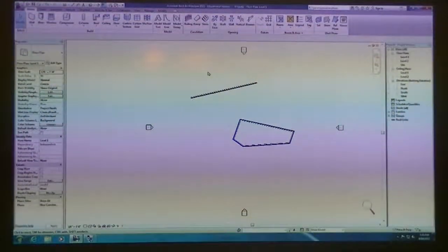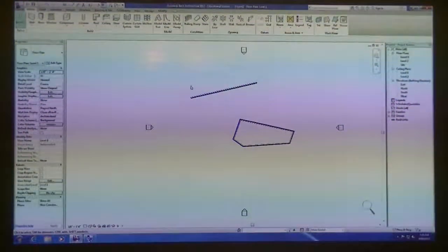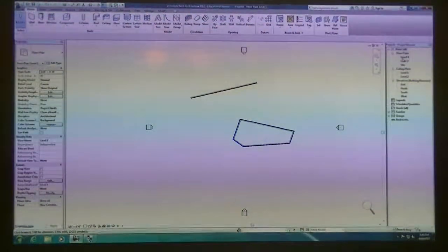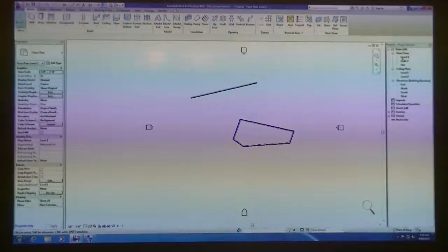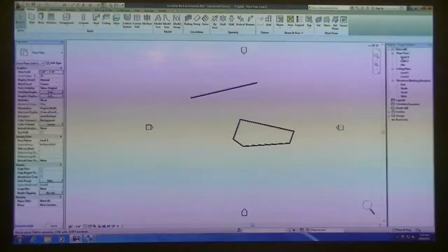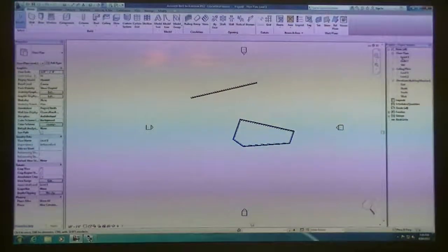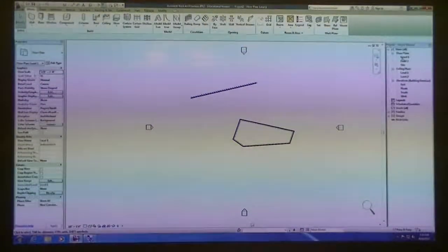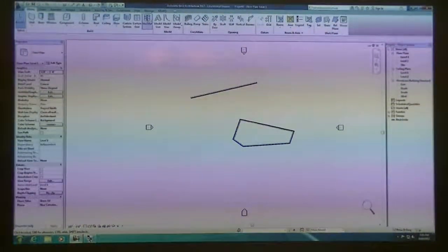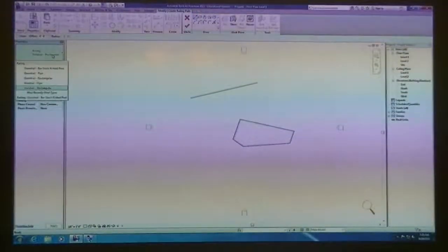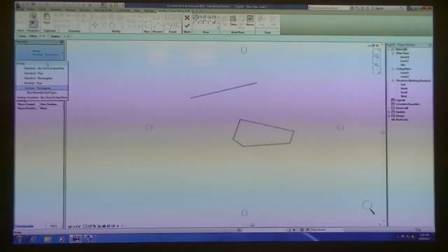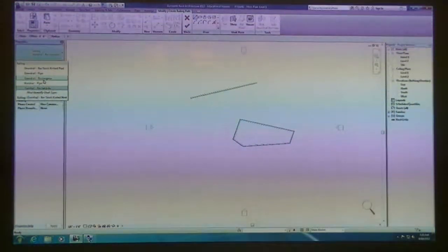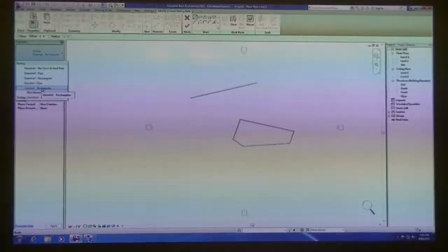Last thing I want to go over, so that gives you a little more understanding of railings. You can start to see that you can develop any design that you really want, as long as you understand how to edit the baluster and look at it in section, and then where to position your railings. Anyone using Revit should never use any of these default railings that come with Revit because they are horrible. You've got that guardrail, that's the pipe rail, and then the vertical pickets, and then the handrails, and all that stuff.